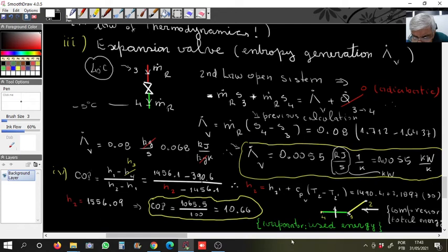Now, this is the evaporator used. This is the used energy. H1 minus H4 is the energy which I used to refrigerate the environment. And 1 to 2 is what I paid for the compressor. I need the compressor to send energy to the fluid. Why? Because I want to transform gas into liquid. I do this using a compressor.